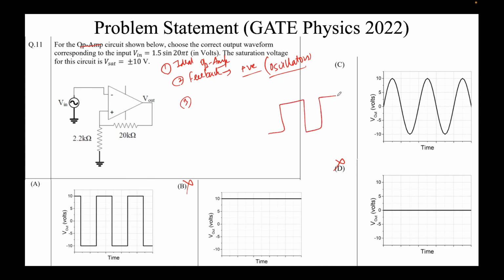oscillators in op amps are not like this, but they will have some slew rate, so it will be like some triangular wedge, not like this. So I know the answer is this, but we'll determine that. Let's start. Since it's an ideal op amp, we'll assume this current is 0, this current is 0, and no current flows out of here. Now we'll try to find the expressions.